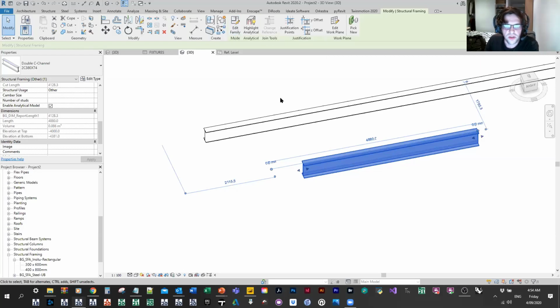Another reason why this might be useful is if you're, say, a structural engineer and you want to do really quick cost takeoff and you know exactly what cost rate this beam has applied to that particular profile type. Well, in this case, you'd want to just embed it in the family probably. You wouldn't want to have to keep going out to Excel and multiplying it with some sort of lookup table. It's much better to find a way to build it in.